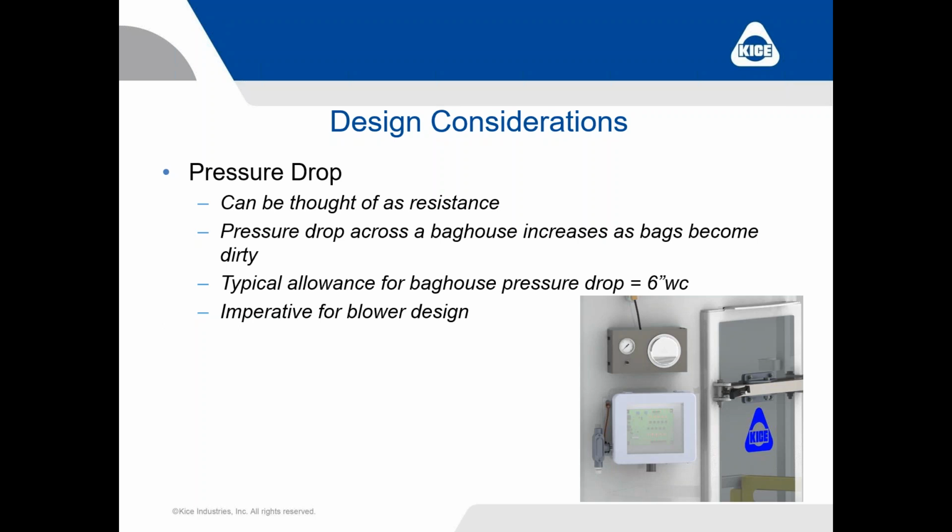Now, when you have a brand new baghouse with brand new bags that have never been run, the effective pressure resistance or pressure drop across a baghouse is going to be 0. You're not going to have any resistance. Your bags are going to be clean.